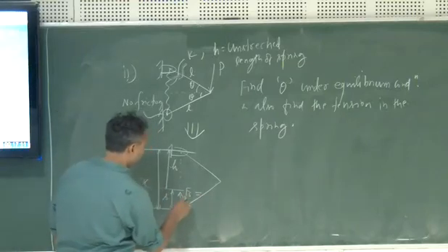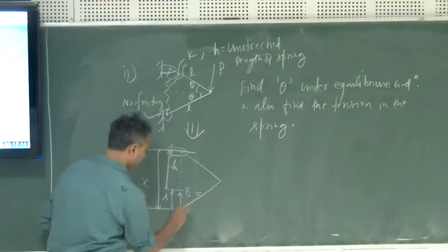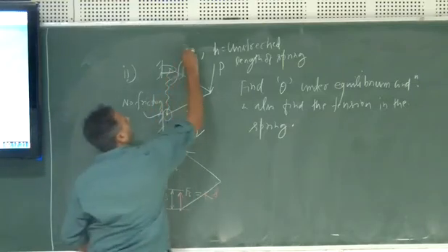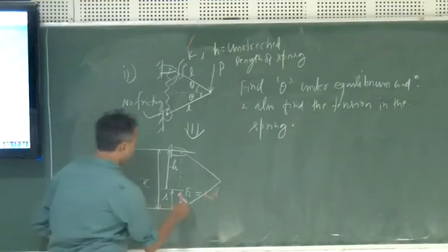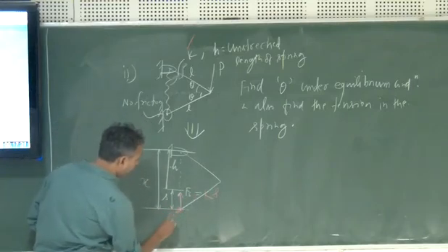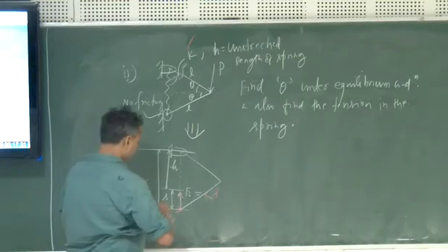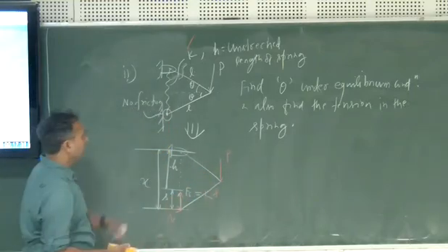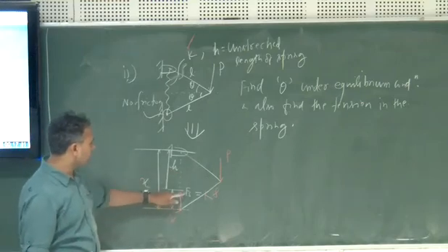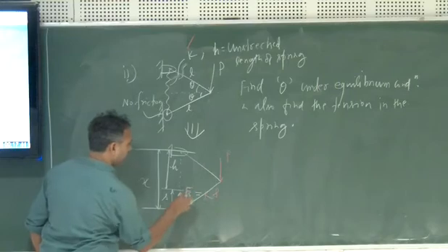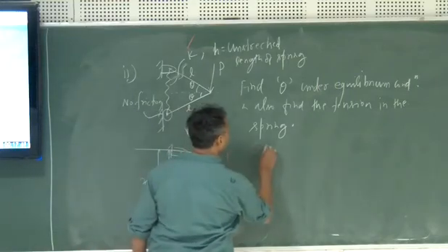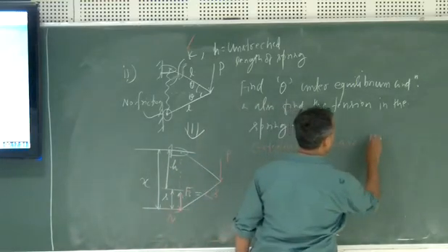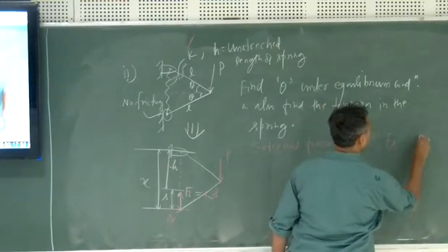Okay. So your force Fs over here will be given by K times S. K is your spring constant which is given, and S is your displacement. And there is also one load which is acting as normal. And this is the actual external force which was acting. Now if we take out this particular thing, there are three external loads. One is your P, another one is your Fs, and third one is your N. So the external forces are P, Fs, and N.